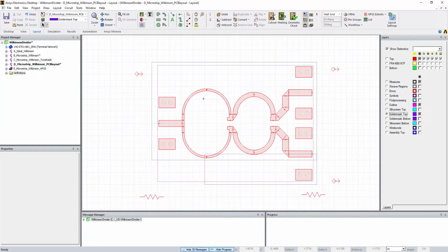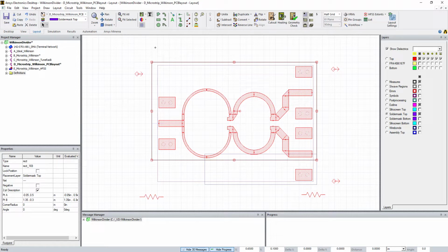So what I'm doing is wherever I draw, now the solder mask layers have to be closed blocks defined by 2 points. But what I'm going to do is wherever I draw a block, see here's a block here, and by the way, the solder mask layers can go beyond this outline layer, just for convenience of drawing. Wherever I draw this box, there will be no solder mask in it.